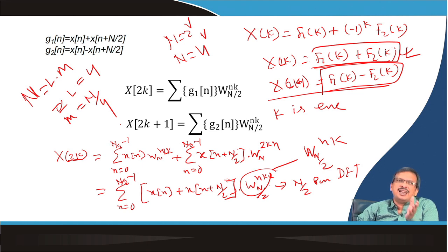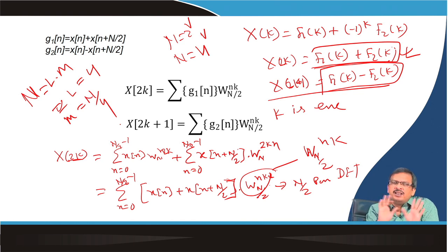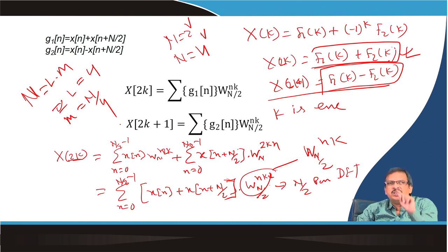Similarly, in decimation in time, I divide the input signal into 4 sequences. When I say decimation in frequency, I get the output as a decimation. So, the input sequence is not jumbled, it is as it is given, and the output sequence I get in jumbled order, which I access in bit reverse mode. Okay. The most common use case is the Radix-2 algorithm. The most used algorithm is the Radix-2 algorithm.